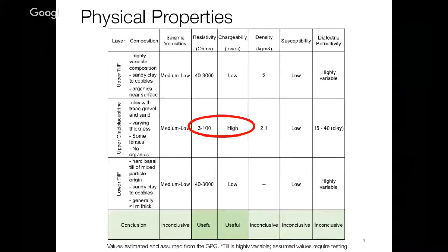And how can that kind of unit make an impact on the breakdown of the dam? Can you explain why that unit is important to characterize? Right, so these properties aren't why the layer failed. The glacial lacustrine layer is clay, which when it was loaded, and you guys can comment on this as well, essentially acts as undrained. It almost solidifies.